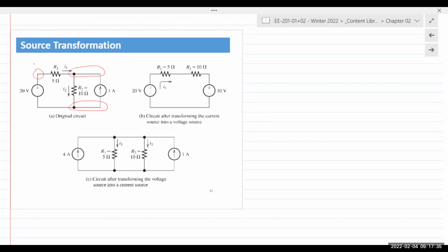So first we establish those facts: that we do have a series connection with the voltage source and a parallel connection with the current source. If those 2 points are not established, we cannot use source transformation. Just want to make sure those points have to be established first, and then you can proceed with that technique. Now, once we have done that, what do we need to do?